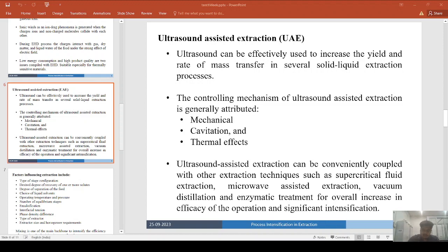Now, ultrasonically assisted extraction can also be coupled with vacuum distillation in order to extract and subsequently concentrate the aroma compounds from natural sources of herbs. It may also give beneficial results of extraction based on the continuous solvent circulation in a dynamic system with ultrasound.